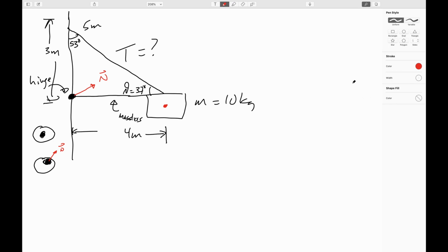All right, so I'm just going to go ahead and draw my forces in here. I've already got my normal force drawn in. I was really close to drawing in my force of gravity from the sign, and we will add in my force due to tension right here. Okay. Now we're going to need the x and the y components of each of these forces. Now, since I don't know the angle that the normal force is pointing yet, my strategy here is I'm just going to say this is nx and that's ny. I'm going to solve for them both, and then this will let me figure out magnitude and direction.